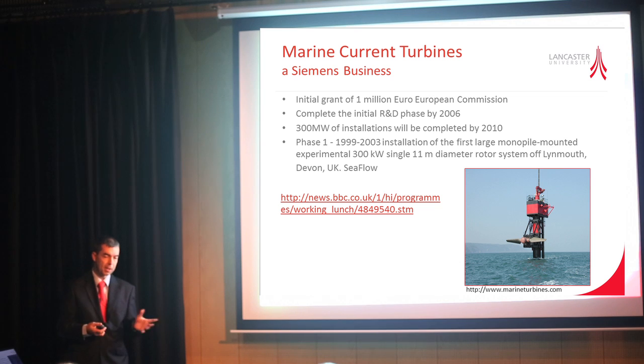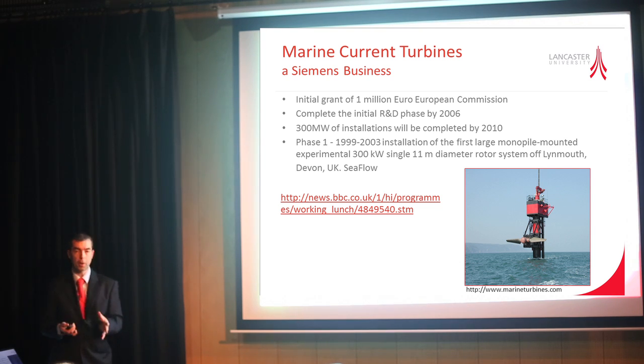The big advantage that they see over other manufacturers is the fact that they oscillate up and down. They scribe, in effect, a rectangular area in terms of the water surface. So in a shallow estuary, where perhaps you're limited by the seabed and the height of water, you're able to capture significantly more of the energy from that, rather than just scribing circles and having a lot of waste in between them.